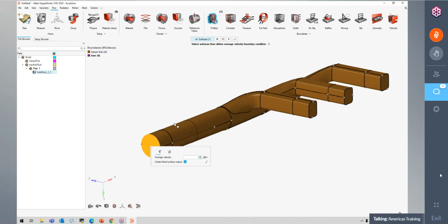So what we want to do is we define this inlet, and we define what the average velocity will be for this. So if I press 2 here, I'll specify a value of 2. And keep in mind that this is all going to be in SI units. Everything is metric. Everything is SI. So you'll be doing meters per second in this case. Temperature is Kelvin, and dimensions are in meters as well. So just keep that in mind for now.